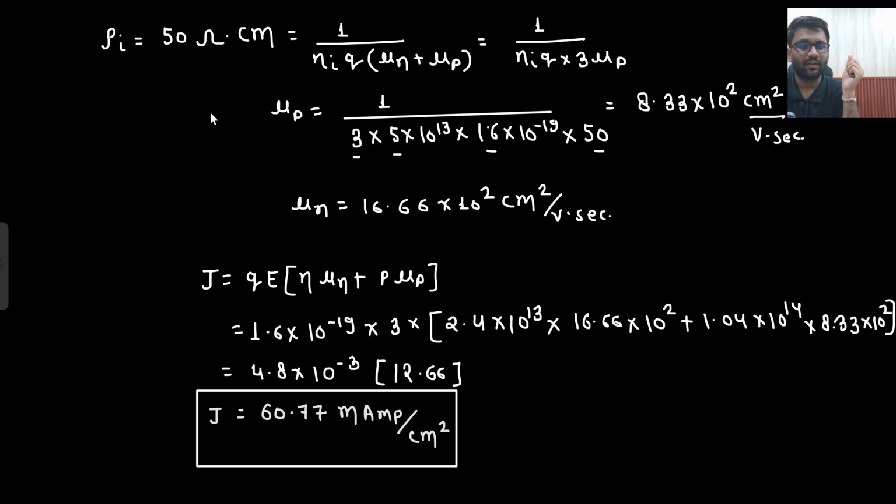Then we studied compensated n type semiconductor and compensated p type semiconductor. In compensated semiconductors, both dopings would be there, but for n type semiconductor, Nd is greater than Na. For p type semiconductor, Na is greater than Nd. For both of them, you can write down the formula of electron concentration and hole concentration just by the formula that you have already remembered.